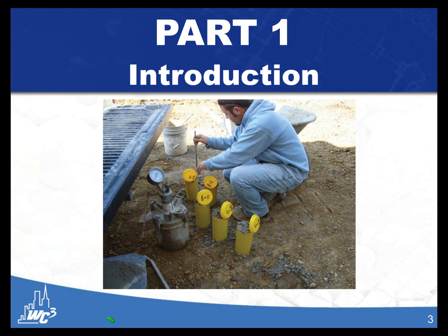In the bottom left-hand corner, and I'll get the pointer. So down here you can see that he already performed the slump test. He's on relatively level ground. He's in the shade. He did an air test, and then right here he's doing his cylinders. So 3 even layers, 25 rods each layer. You tap the sides 10 to 15 times with the hand or with the mallet. Level it off. Supposed to keep it in similar conditions as to what's out on the job site.